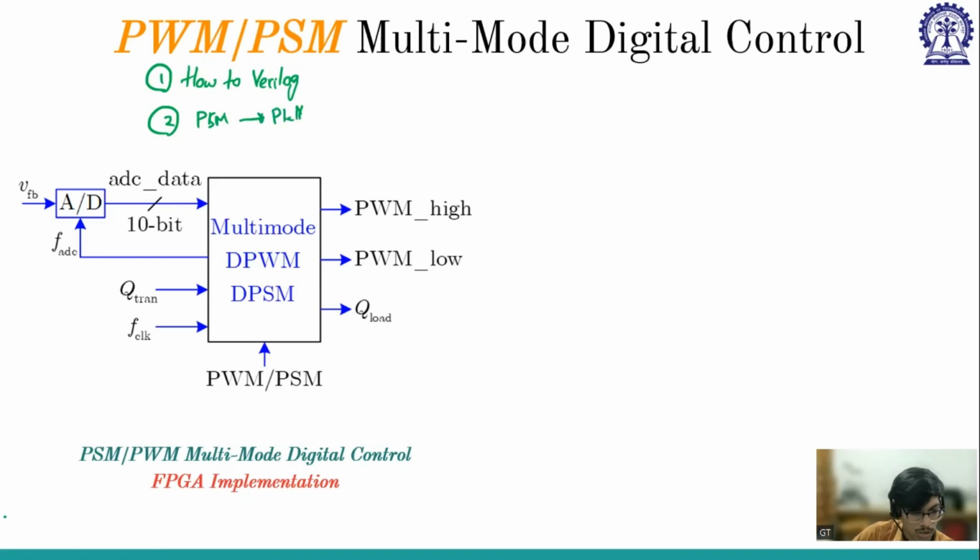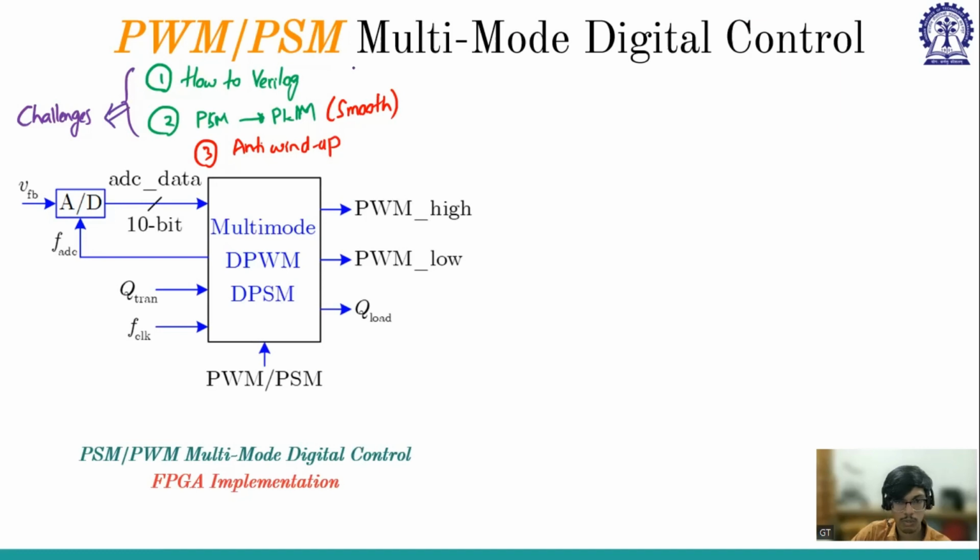The transitions should be smooth, and how it is happening, all these aspects are the challenges. And there is something called integrator wind up, so there should be something called anti wind up, which we'll again discuss in the upcoming week. So these are some of the challenges when it comes to the multi-mode digital control.